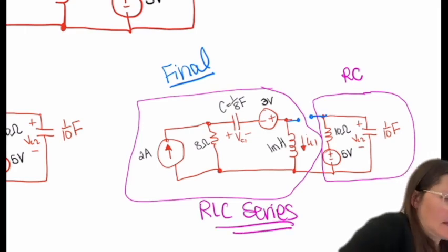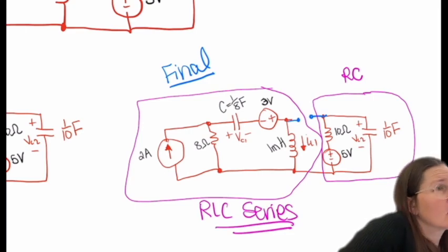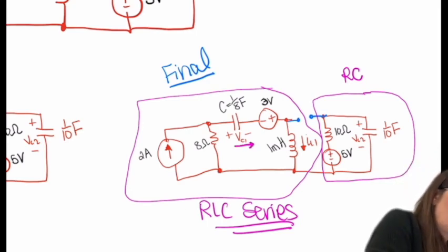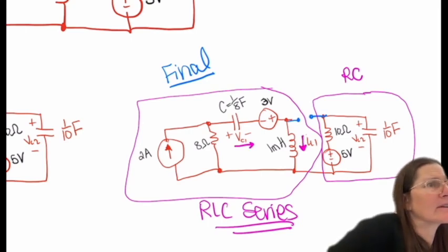Okay, because while there is weird shenanigans of different current going through the resistor, the capacitor, and the inductor, they have the same current through it, and that's all we need to qualify as series. Correct. Yep, so the same current is flowing through the capacitor here as it is through the inductor. That is what determines it's in series.